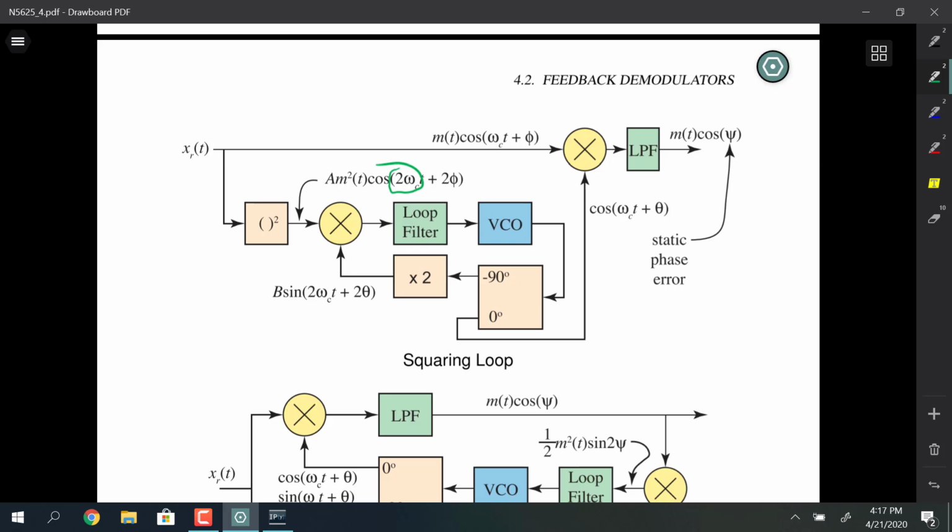We take the output of our VCO and square it. Send it into a frequency doubler. So we're going to lock onto the doubled VCO frequency. And then the 0 degree phase output from this quadrature hybrid, because remember a loop locks with a 90 degree phase shift, then we use that as a coherent reference, and maybe have to do some phase shift adjustment to get this phase error to 0.